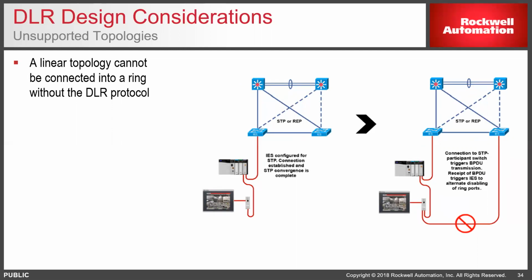Similarly, on a single linear network, you can create the same issue by adding that extra port, extra cable, and you've now made a loop in the network that is going to cause packet storms and things like that, which the system would have to try to automatically filter out and wouldn't really know what to do with. So again, if you added in an additional DLR link in between those switches and made this a separate DLR, that would make that a valid topology.